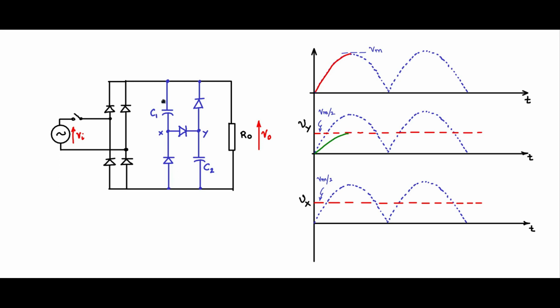Now once it is charged fully here, then the input voltage would have gone low. These diodes would be reverse biased under the normal condition if it was a normal circuit. But now let us say it gets reversed by reverse condition, then this capacitor starts discharging, during which time the diode conducts. The capacitor is charged to only half the voltage, Vm by 2. This also Vm by 2. So this node potential V0 will go to Vm by 2.